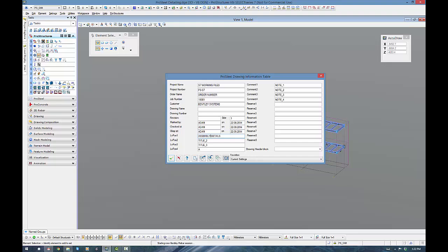But if you want to get really tricky, you know that there's beams on there, so you could maybe call it beam details. To be honest with you though, just be really careful with that, because if you then turn beams off and columns on and you forget to change that, it gets a bit embarrassing. So personally, I'm a big fan of leaving it as assembly. That way I don't get caught.